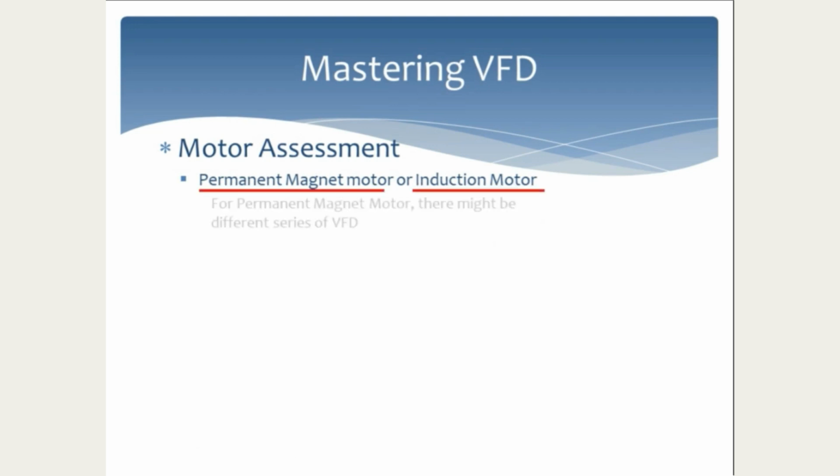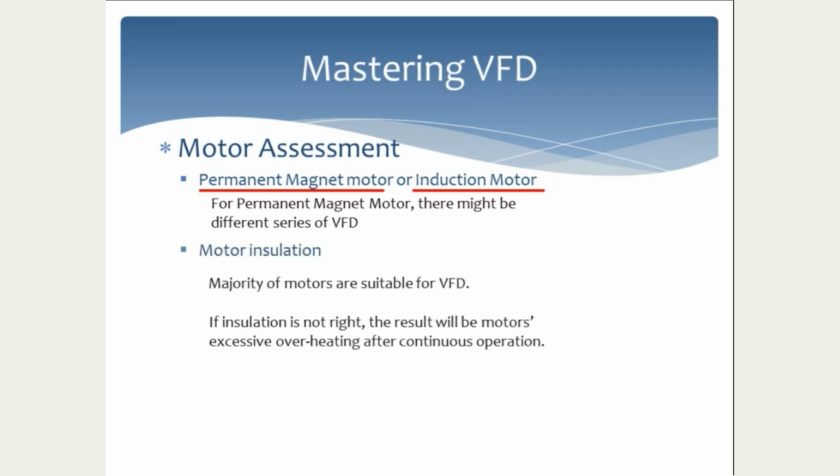Lastly, the motor assessment. We need to know if the motor is an induction motor or a permanent magnet motor. For a permanent magnet motor, the VFD should have the capability. And second, the motor type. Nowadays, the majority of motors are suitable for VFD. We can encounter an old motor which might not be suitable for VFD, or a motor that is rewound and might not be suitable for VFD.